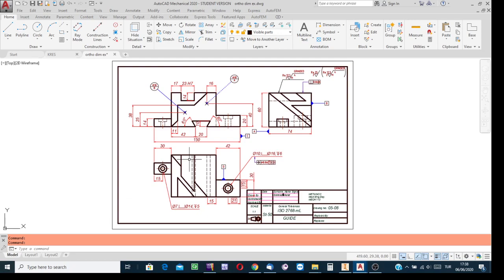In hand drafting, to be able to draw, for instance, this view, this projection, using the rules and the T-square and mainly a pencil, we draw the lines. Moving the point of the pencil along the edge of the ruler or T-square, we draw straight lines. For the circles, we use a compass.